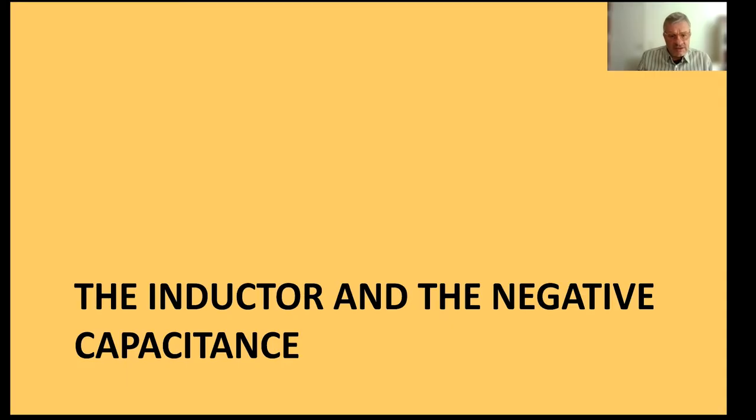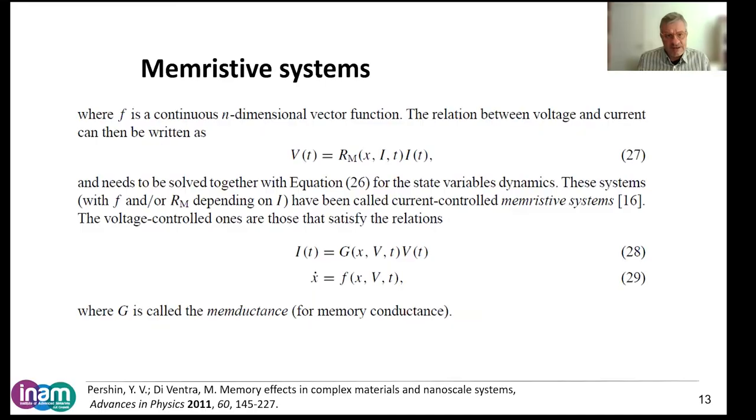We have to understand the response of certain basic elements. And in the case of a memristor, we have two equations. One is a current voltage equation, and there's a memory variable. And this memory variable has another relaxation equation that will say how it responds to the external voltage. So this pair of equations is a minimal model also for neurons, and this is our starting point.